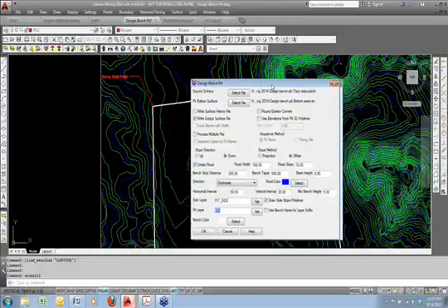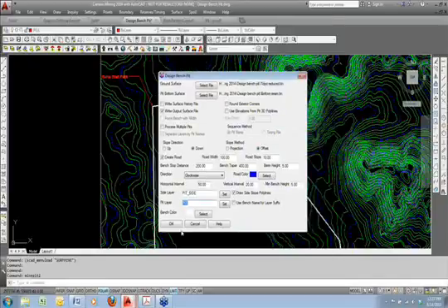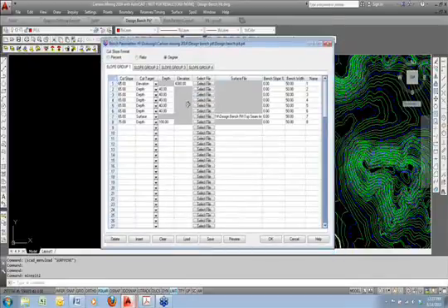And then we hit OK to get to the next screen, which is your template of your slopes, your angles, your bench widths. And so I'm starting at the top, and I'm going down to elevation 4380. And then I'm going to run a series of 40 tall benches. Then I'm going to hit another tin file. You can use tins to bench to. And then I'll go down to the bottom. All my benches will be flat at 0 slope. They'll be 50 wide, and you can give them names.